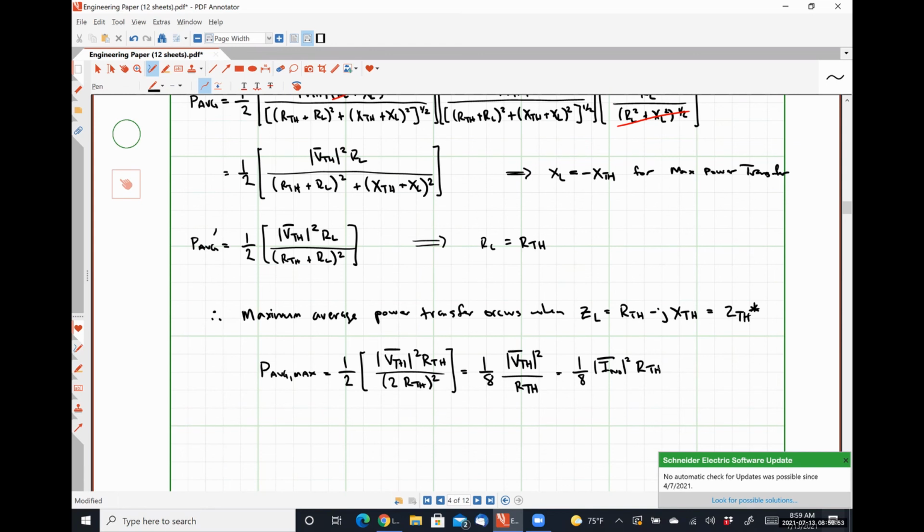The exponential is occurring because the voltage drop across the capacitor and the current flowing through the inductor cannot change abruptly, because to do so would cause an infinite transfer of energy. So they store energy and gradually release it back into the system. Another way of thinking about why a capacitor voltage can't change abruptly and why an inductor current can't change abruptly is because it takes time to transfer energy.